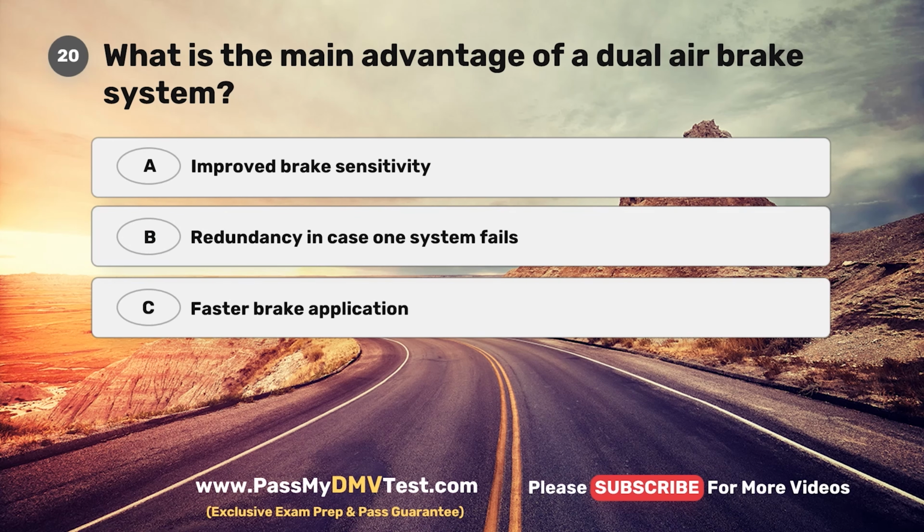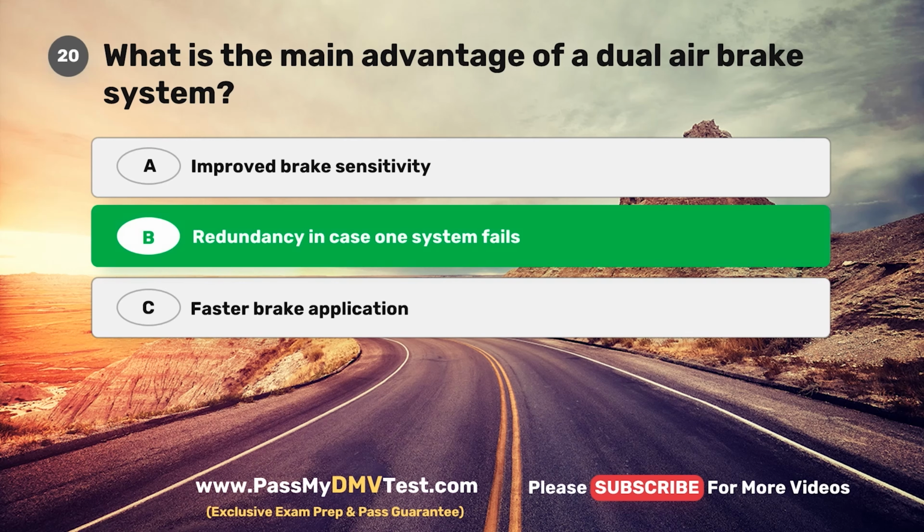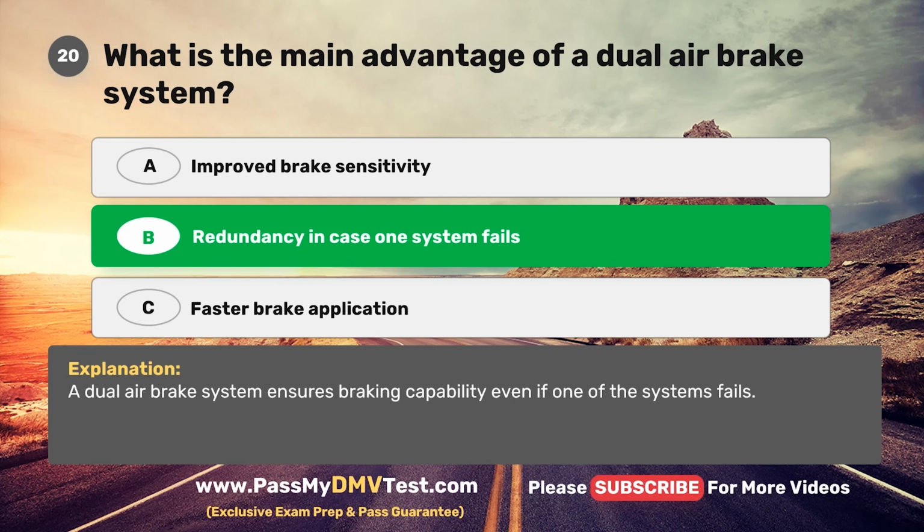Question 20. What is the main advantage of a dual air brake system? A. Improved brake sensitivity. B. Redundancy in case one system fails. C. Faster brake application. The correct answer is B, redundancy in case one system fails. A dual air brake system ensures braking capability even if one of the systems fails.